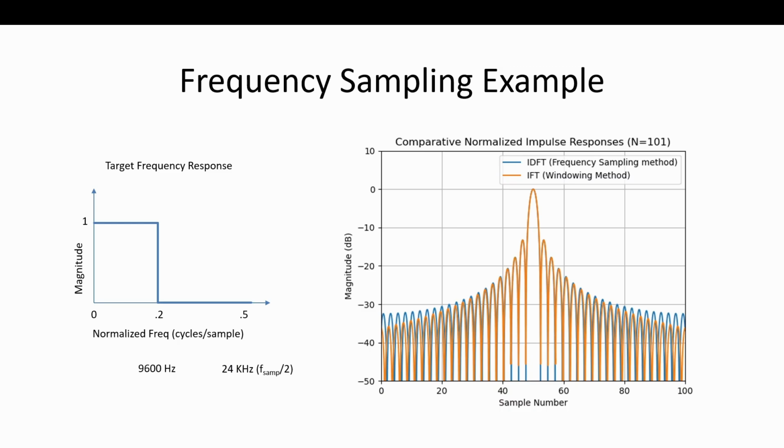And this is putting some actual quantity on it in terms of how much difference does it make. So what you're seeing is the comparative response. This is the impulse response you would get, and this is in dB. You should look at your impulse responses in dB to see the actual distortion levels they're talking about. If I looked at that as a magnitude, you didn't see any of the stuff.